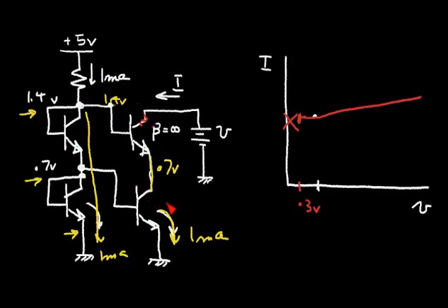So the key thing is that the operating point on this transistor is at a point. It's not going to change very much. I can change this voltage here quite a bit. But the operating point on this transistor here that controls the current doesn't change much. So in this case, the current will be very flat. It won't have this high slope here. But my operating voltage will be not as good.